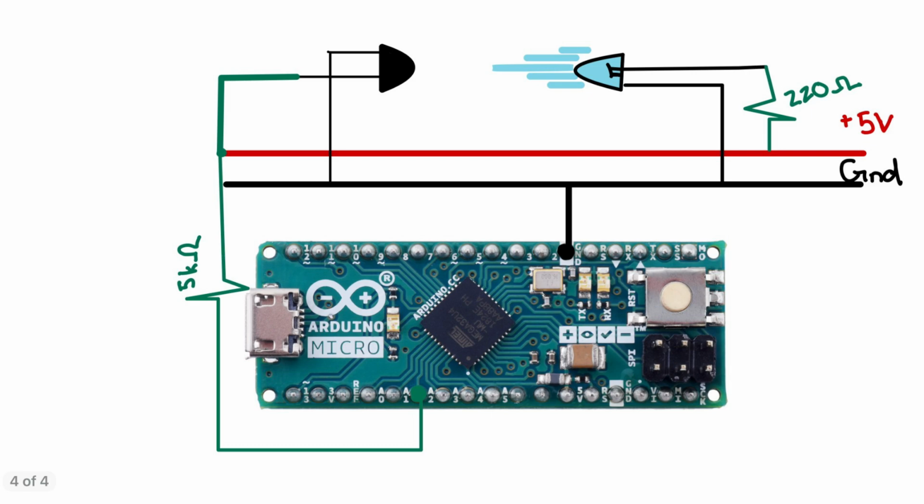You'll see I had to tie the Arduino ground to that ground so the analog reference doesn't become unstable. And for the IR diode, I just have it directly connected to a 5-volt pointing directly at the photoresistor. Now, when something gets in the way of it, you'll notice that it blocks, and my analog pin will be able to differentiate that.